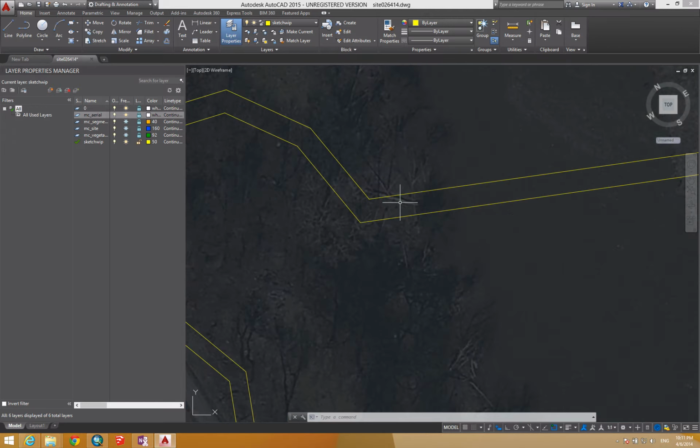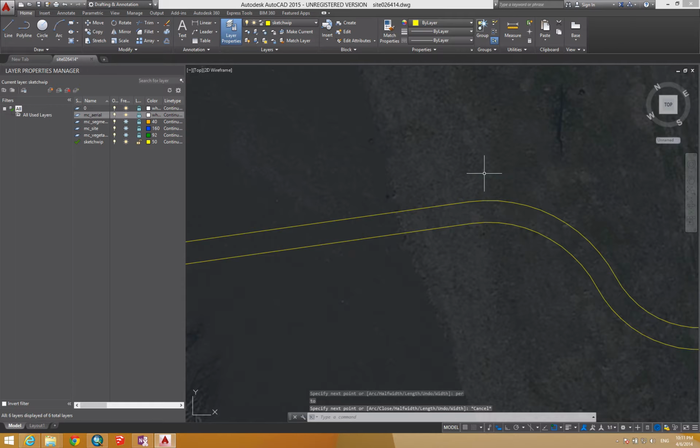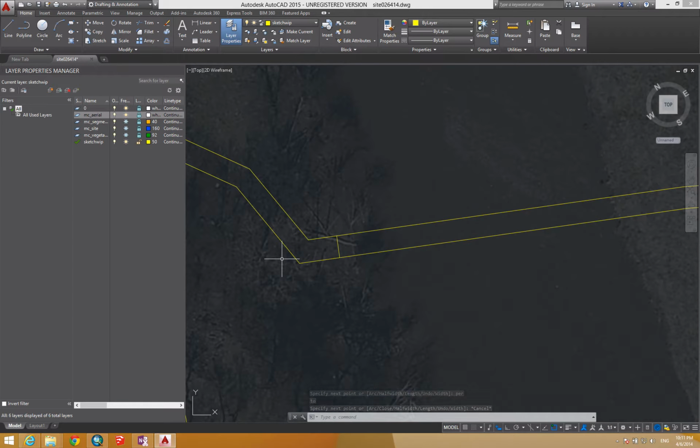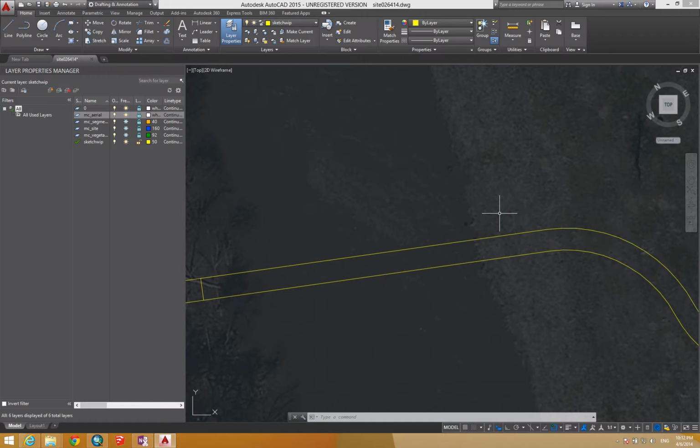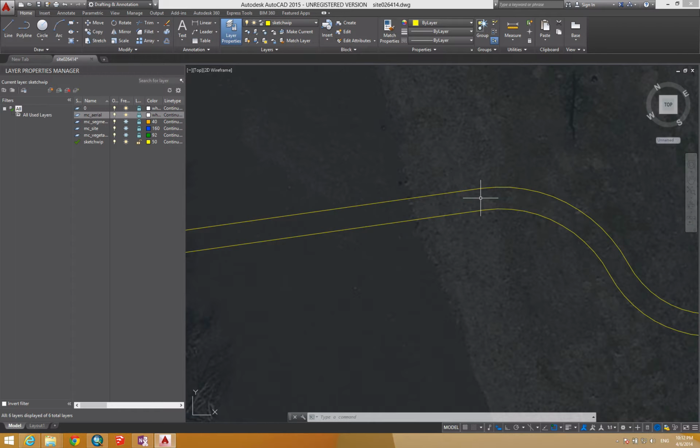So I will load up my polyline again, P-L-I-N-E, and I'll start with an NEA, which is for near, and then I'll type PER for perpendicular, and that will draw me a line perpendicular. Really important, you'll see why. You don't want to just eye this, just trust me. And that's why it's nice to load up those commands on the fly, because near and perpendicular are honestly not very common snaps that you would use very much. So I like to type them in. They've all got fairly conventional and, as you would expect, shortcut 3-character combinations.